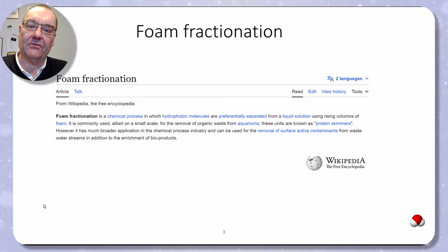So the hydrophobic part of the PFAS will make it very suitable for removing by foam fractionation. And just a note, foam fractionation has been used many years before the PFAS problem came along, to remove proteins and clean water, for instance, from fish farms and so on. So again, foam fractionation is not something new or an innovative method just for PFAS. It's actually used long before, which benefits us now when we apply this method for PFAS separation.